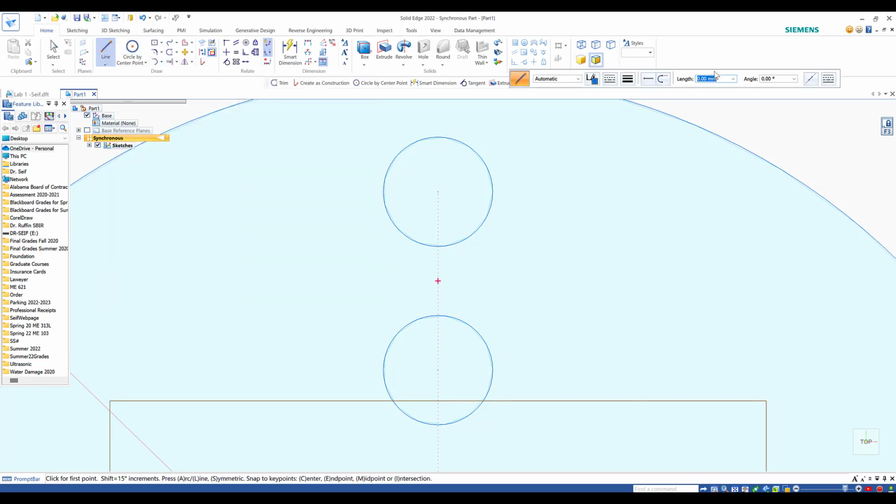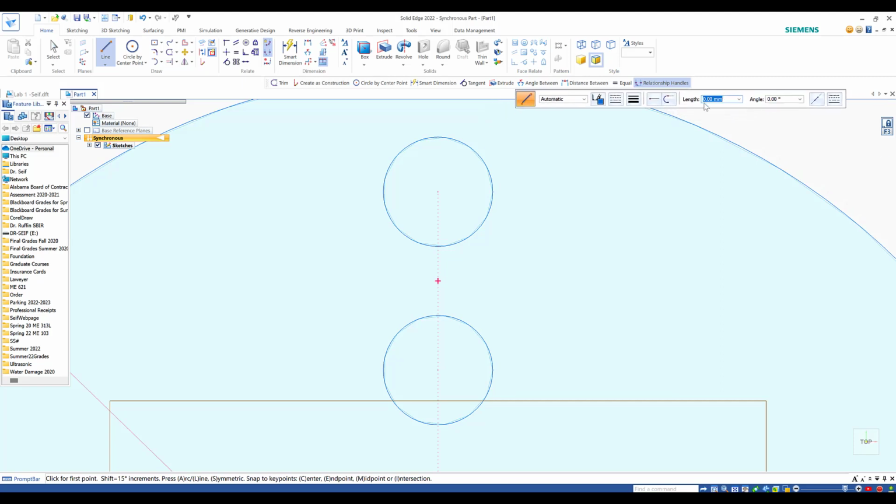and you will see the menu for the line. I'm going to just leave it to the side, and the way to do it is I'm going to click at any point, and it should move with you. If it is moving with me, it means that I did not choose a feature point. Now I'm going to go down, come closer to the other circle. When I see two symbols, it means it is tangent and intersecting, so I'm going to click.